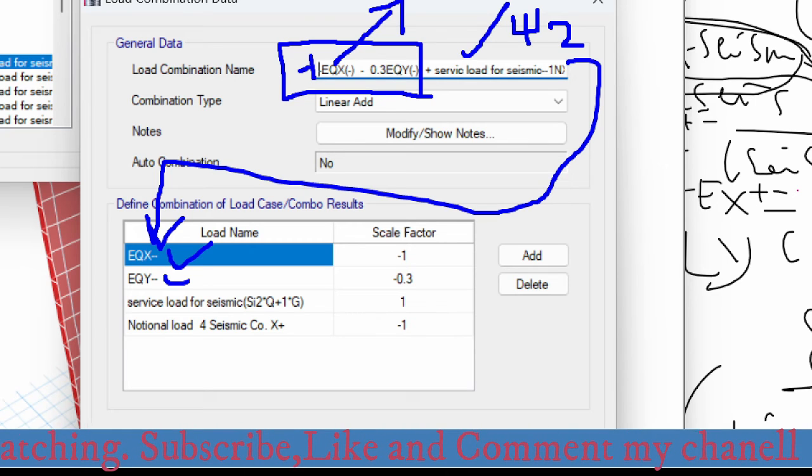And here, this one is EQY minus, meaning 30% of the seismic load in negative y direction will be combined with 100% of the seismic load in negative x direction.